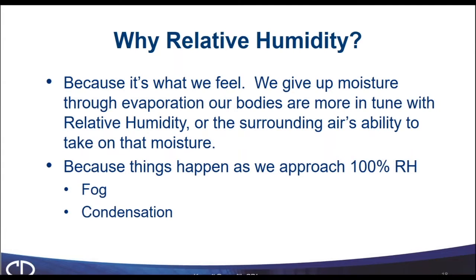So if you're in Arizona and the temperature is 90 degrees, but the relative humidity is down around 20%, as compared to Minnesota in the summertime where it's maybe a cooler temperature, let's say 80 degrees, but now it's 60% relative humidity. In the Arizona condition, drier, we're going to give up that evaporated moisture from our bodies more easily and therefore feel cooler compared to the Minnesota condition where it just feels quite hot and sweaty. So relative humidity is what you feel.